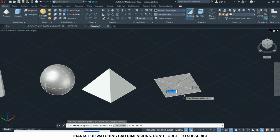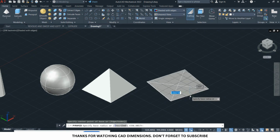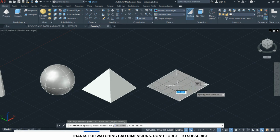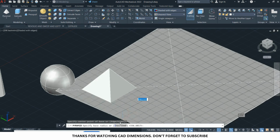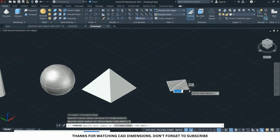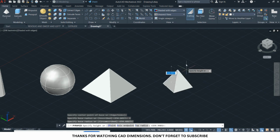Now if you look at this particular pyramid, you realize that once I specify the point, the next point is actually pointing to the midpoint of the edge or the line. Okay, let's see something. So come to the inscribe, click inscribe, then you realize that now the point is with respect to the vectors, the corner. All right, so that is for the inscribe. So you can actually specify with respect to inscribe or circumscribe. So that's what I want to show you with respect to pyramid.